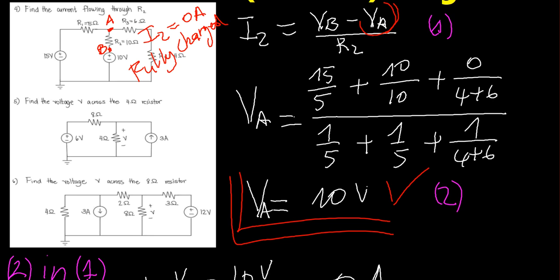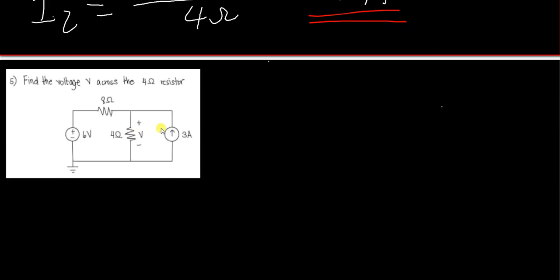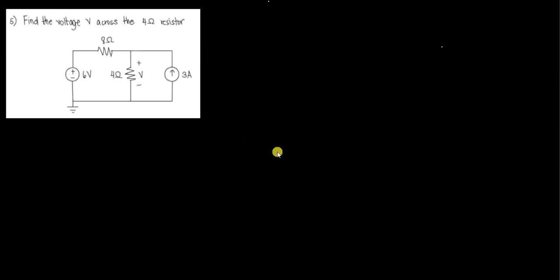Here the process for me is to transform this Thévenin source into Norton source, so that I will be able to add the 2 Norton sources and make a current divider and get the current flowing through the 4 ohm resistor. At the end, apply Ohm's law and get the voltage across the 4 ohms resistor. So we are going to redraw that circuit to perform it very well. I was saying that the aim here is first of all to transform the Thévenin source into Norton source.